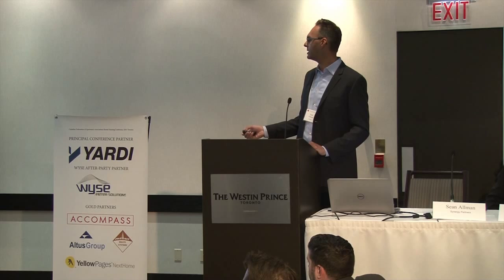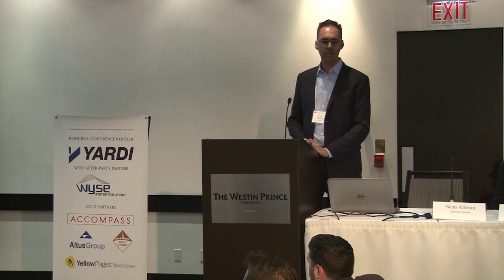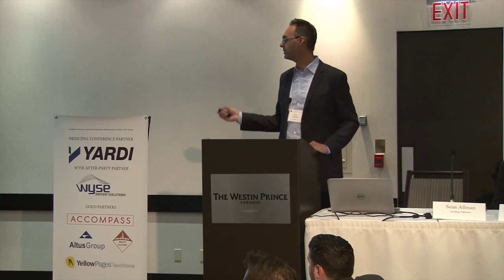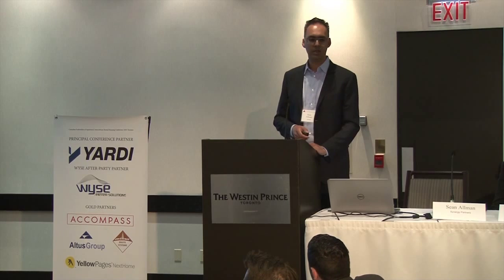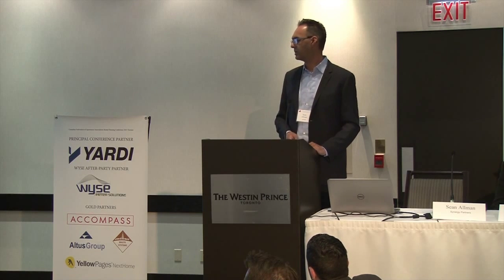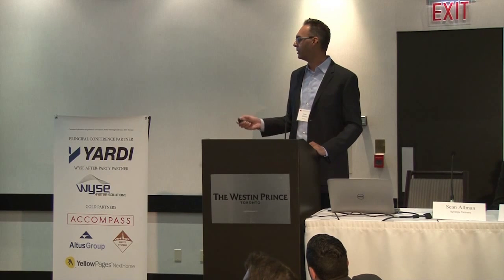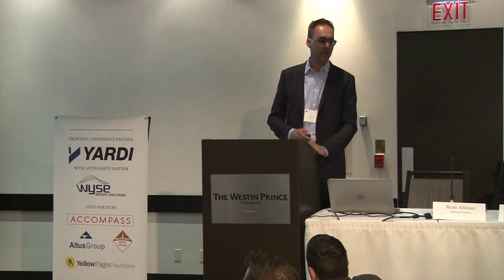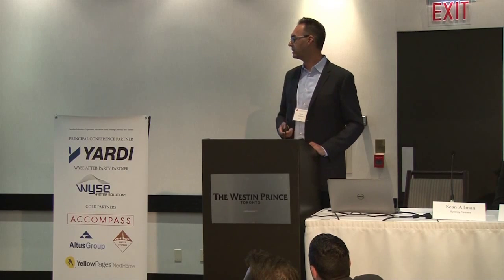But this needs to be carefully evaluated. Older garages where there's potential for concrete delaminations, corrosion, especially on roof slabs or parking decks. Not roof slabs with landscaped areas, they're of much lower risk, in the case where they haven't increased the overburden over the years. But where you have the potential for corrosion right around the column to slab interface, it has to be checked on a regular basis. You have to understand the construction, and you have to understand the risk.